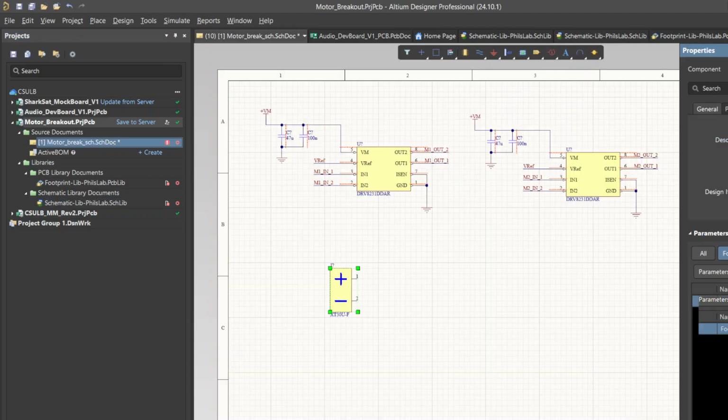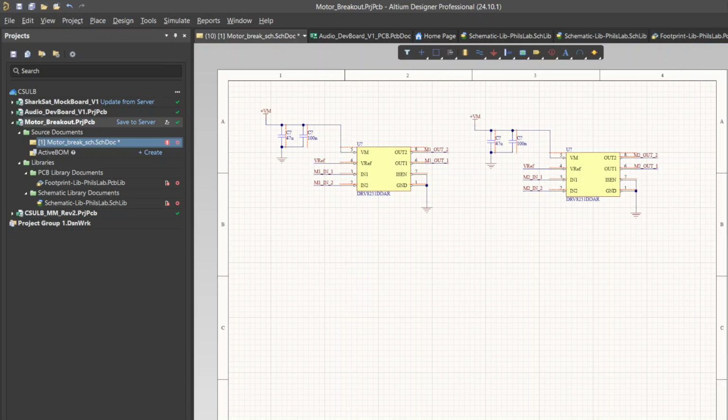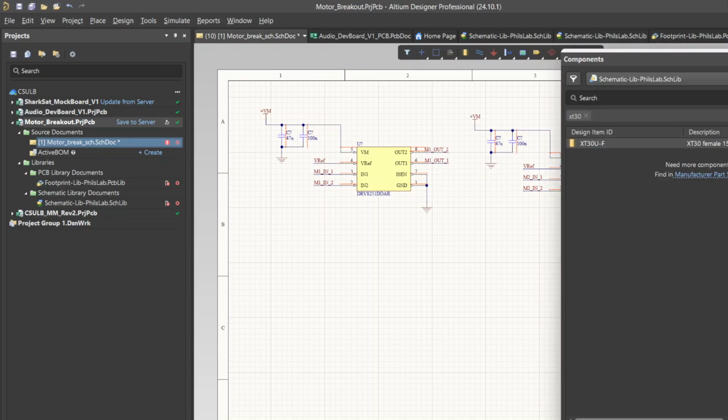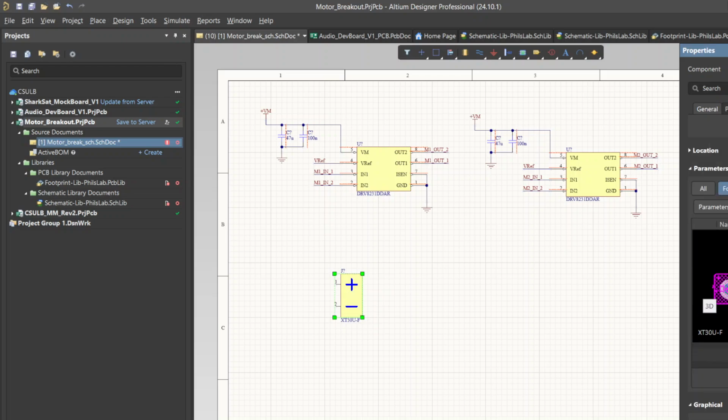And again, you'll notice that we only really have this footprint here. However, if we go ahead and delete it and add another one, here it is. Let's double click it and let's go ahead and now under the value, we can change our schematic footprint or our PCB footprint.